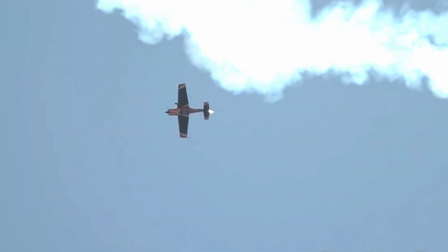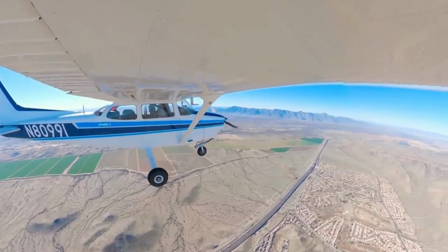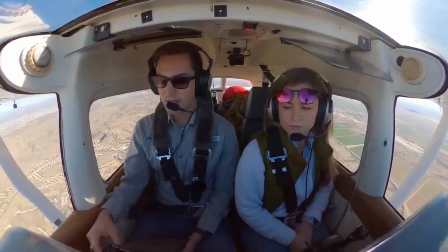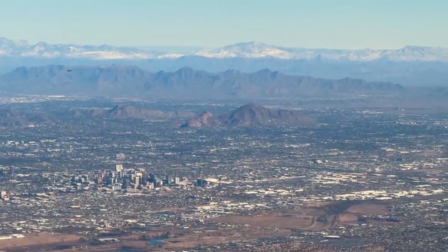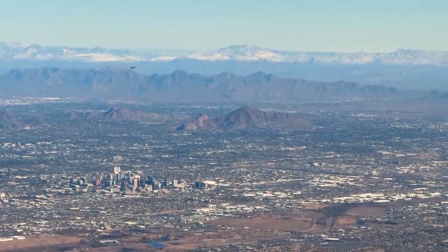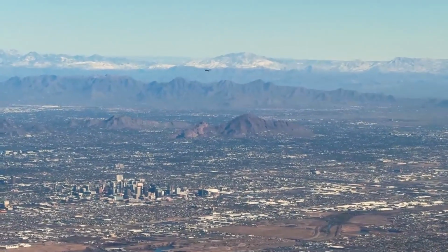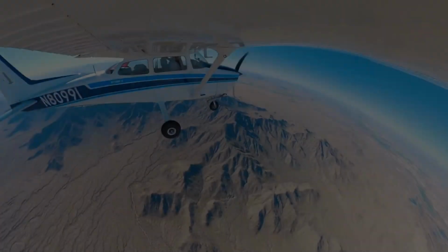Skin friction drag. Covering the entire wetted surface of the aircraft is a thin layer of air called a boundary layer. The air molecules on the surface have zero velocity in relation to the surface. However, the layer just above moves over the stagnant molecules below because it is pulled along by a third layer close to the free stream of air.